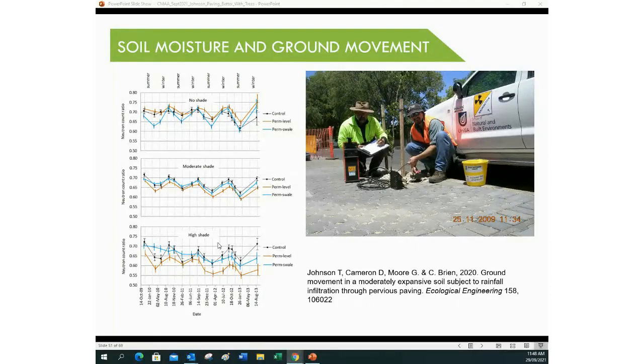Evaporation in Adelaide is 3 times what rainfall is. So having an impervious ventilated surface, the soil was generally drier on average below the permeable pavement than wetter. So the assumption that it will always be wetter under permeable paving because it lets the water in is just wrong. We monitored these seasonally 4 times a year minimum, sometimes up to 8 times in some years.